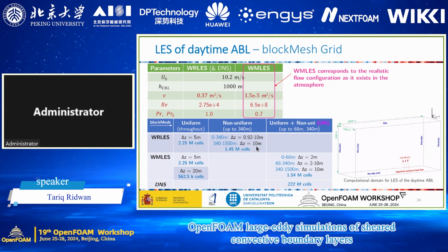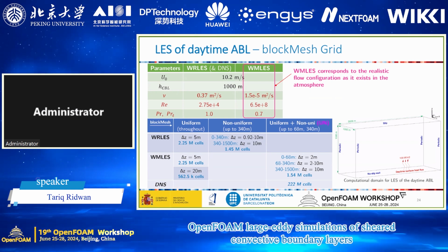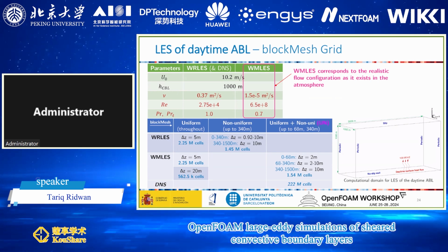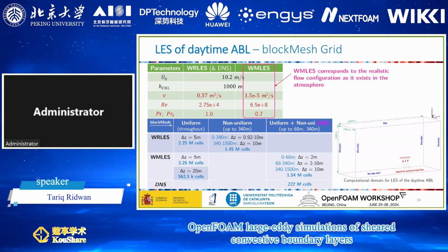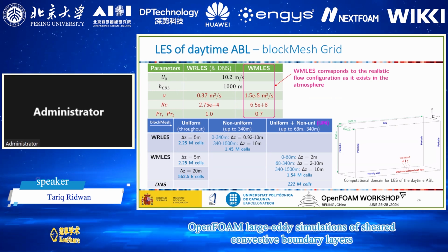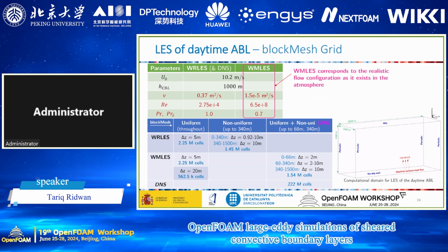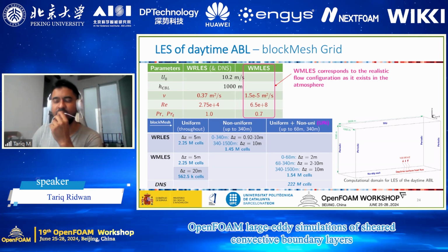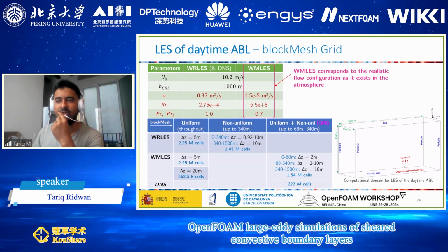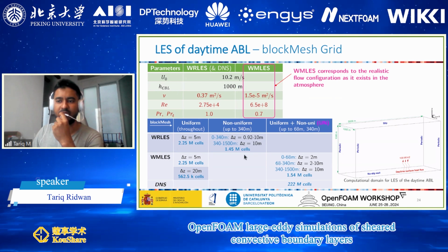My question is that there is no obvious priority for the Vreman model over the regular Smagorinsky model in this kind of simulation, right? If you look at the velocity profile, look at the other quantities. So yes, no. So the most commonly used Smagorinsky model seems better in some cases than the Vreman model, right? Exactly. That is why we stick with Smagorinsky. Can you give some comment on that? So the classical Smagorinsky is actually working better than the Vreman model, and that is why we are sticking with Smagorinsky for the wall model LES.